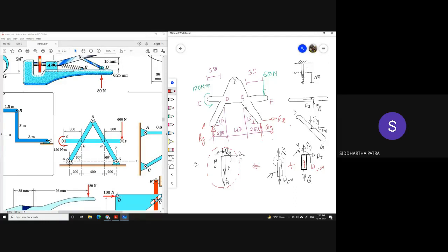Now my question is that for this entire structure, you can write 3 equations of equilibrium. That means basically you can reduce it to an equivalent force system, which will have three components, two force components and a moment component. For equilibrium, all those components are zero. So you have two force equations and one moment equation, known as the equations of equilibrium. By setting those to zero, you can solve for ay, gy, and gx, right? So has anyone already solved it?